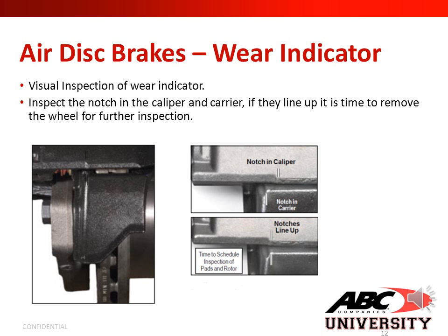Let's go over your air disc brakes wear indicator. Visual inspection of the wear indicator. Inspect the notch in the caliper and carrier. If they line up, it is time to remove the wheel for further inspection. Note the pictures below.